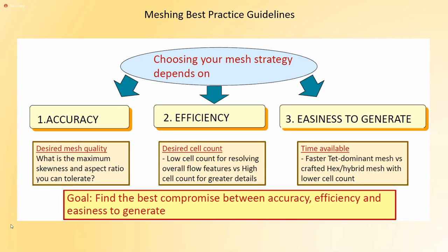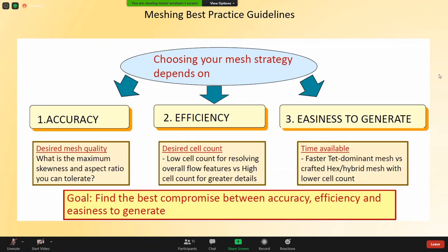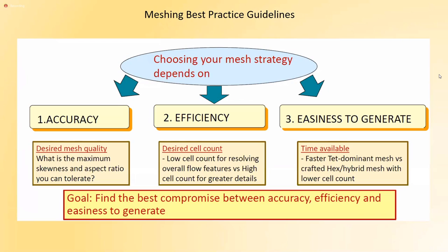And then you have polyhex core, which means you have two layers connecting the boundary layer with polyhedras, which are not prism, to the hex core. And the hex core is simply a cut cell. I mean, it's not body fitted. So if you have curved flow, swirling flow, then using hex core is not so good, because you don't get anything from using hex core.